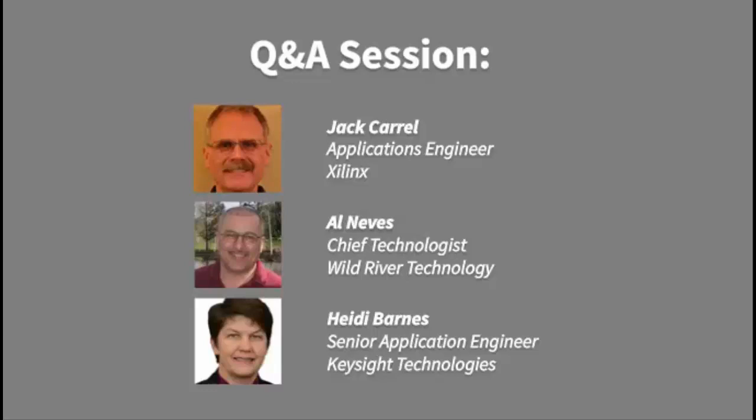So I think I answered your question. They need to be localized. They need to be low return loss. And the pad, the anti-pad, the spacing, the drill diameter, and all of that needs to be done correctly. And they need to be back drilled, otherwise you'll have a quarter half-wave resonance that wreaks havoc with these systems, especially 56 gig PAM4, which is very sensitive to via signal integrity issues.